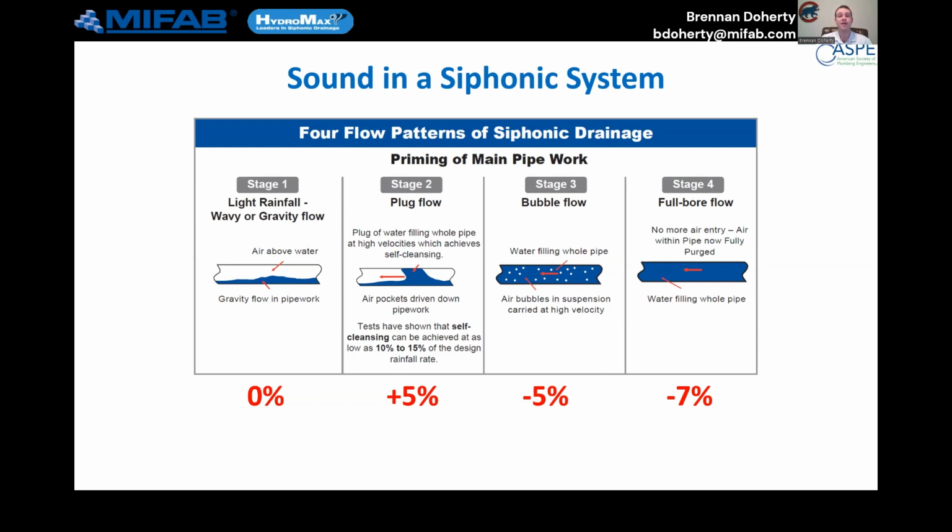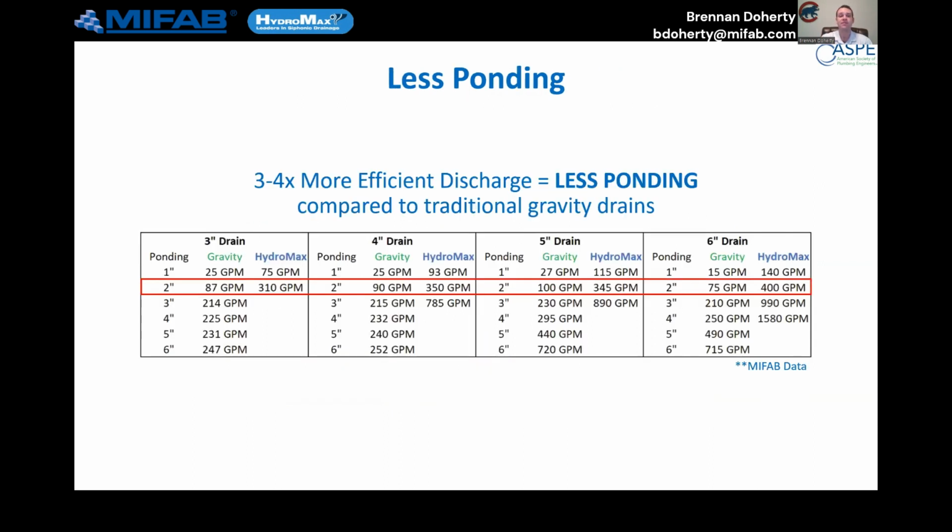We did ask Charlotte Pipe about this, and their comment was cast iron over PVC with insulation being your next best friend. But the reality is, if we have somewhere with that noise concern, an auditorium, penthouse, C-suite offices in that hospital unit, with gravity, we're dictated by pitch. We have to go wherever that pipe tells us within our design. With siphonic, at least we can route that pipe out of there as fast as humanly possible, adding something to our design toolbox we do not currently have.